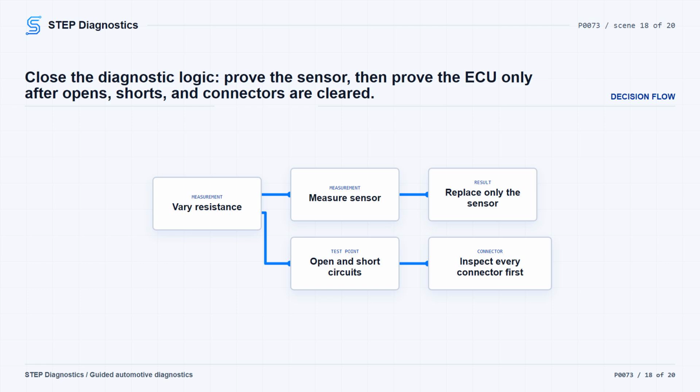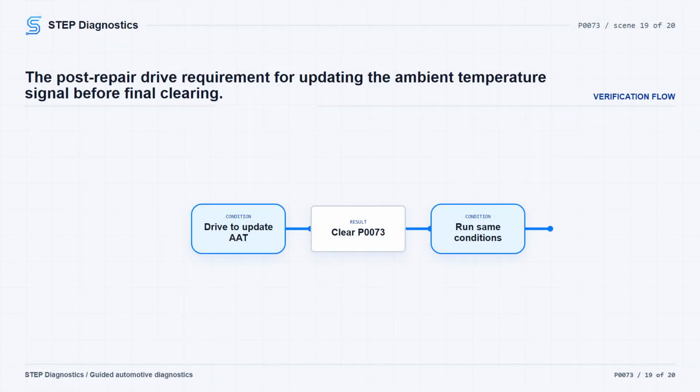is indicated as faulty. Before condemning the ECU, carefully inspect all connectors in the circuit path for water intrusion, spread terminals, pushed-out terminals, burnt terminals, or corrosion. Also remember the ambient air temperature sensor is individually serviceable. If measured sensor resistance does not match the temperature resistance data, the sensor is the serviceable part, not the entire mirror assembly. Keep verification separate from the testing.